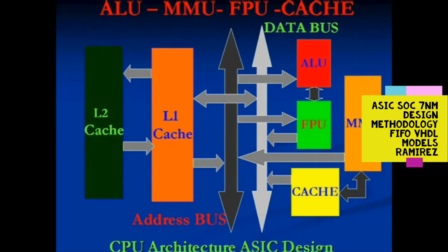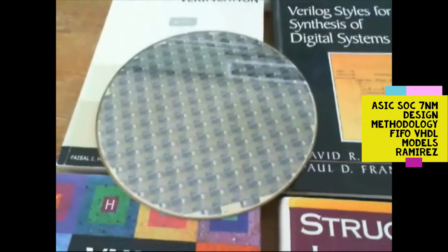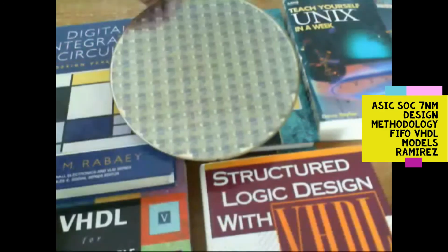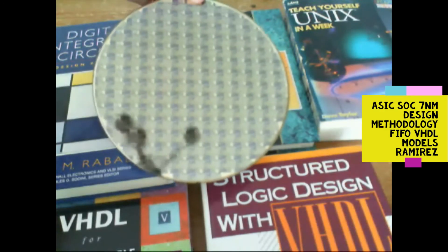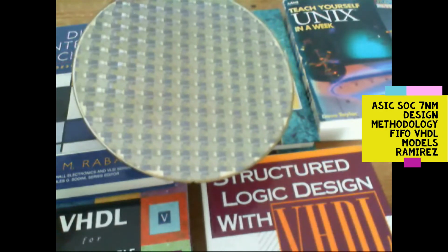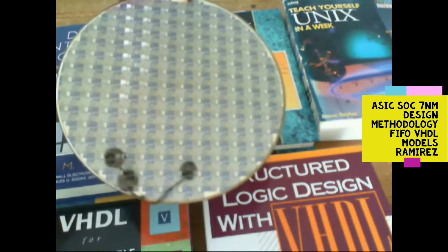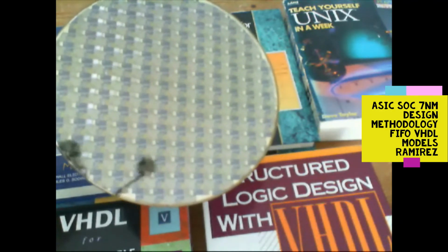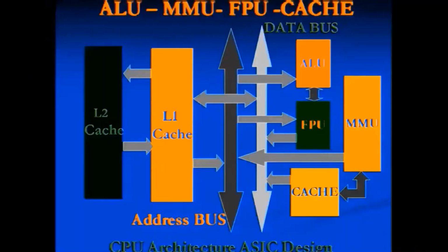Finally, the file produced at the output of the layout is the GDS2 file, which is the file used by the foundry to fabricate the silicon. The layout should be done according to silicon foundry design rules.